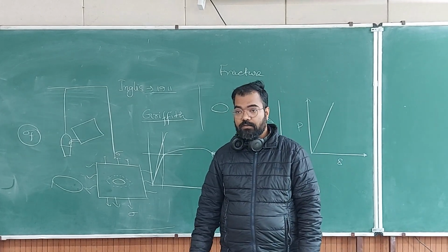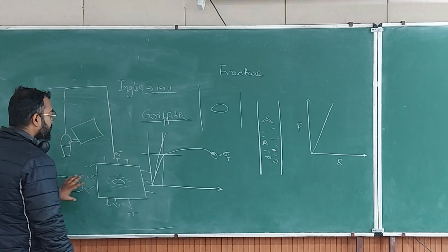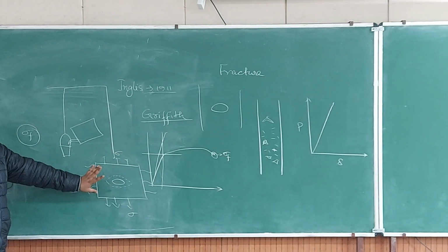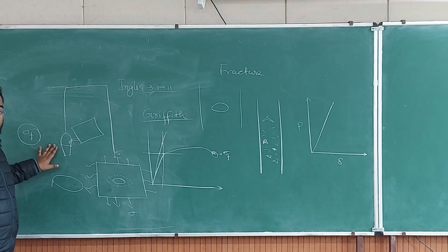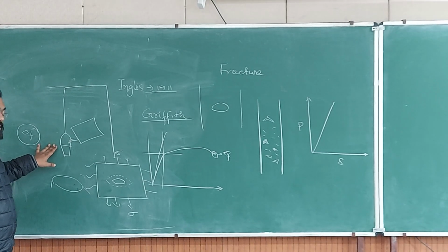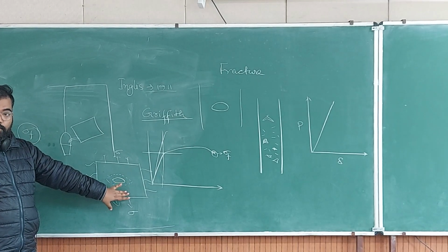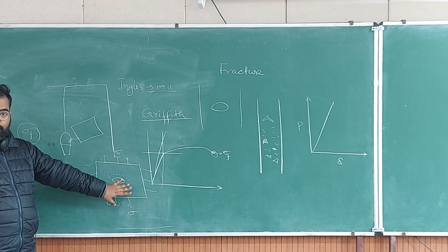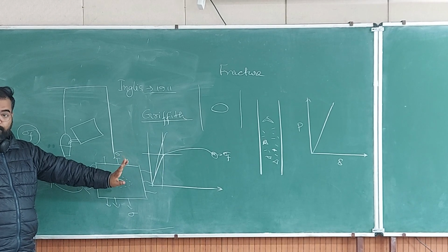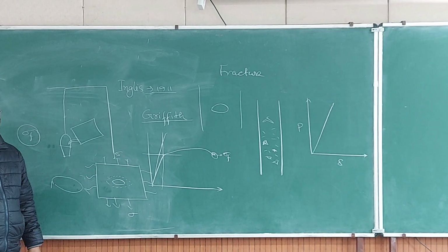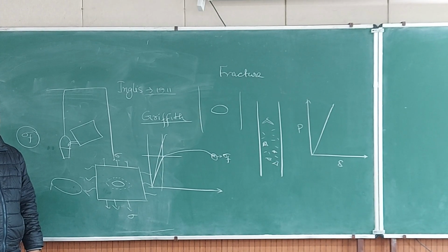Will it not? Initially you load this plate, you apply force on it, and you keep on increasing the force, like Vinci is doing. Then the crack grows a certain amount. What will happen to the force? Will you have to increase the force now, or will there be a sudden drop in force? Why? Why will there be a drop?